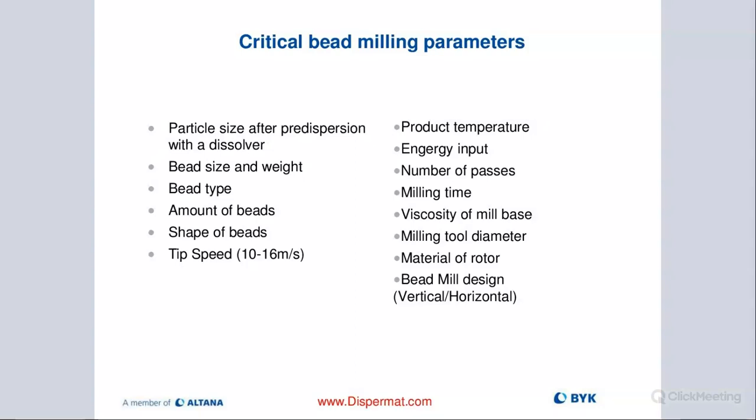So therefore, if you're making a white product, it could turn gray if you don't use ceramic and you're milling for a long time. Then you would definitely see bleeding from the milling chamber or the stainless steel rotor into your slurry. And we actually have seen it where beautiful white looked gray when they were done milling. So everything had to be changed over to a ceramic rotor, or at least a ceramic milling chamber.